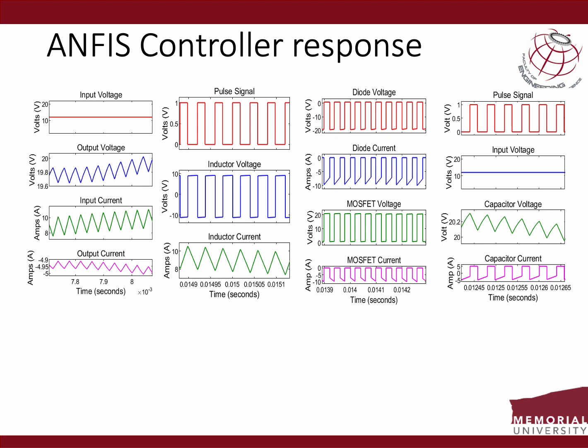During the simulation, we were also interested in the response for the voltage and the diode current. We were also interested in the voltages across the MOSFET and the capacitor. So all these were plotted, and we realized that the theoretical waveform and the waveform generated from our oscilloscope or our scopes were in sync, were correct, were in line. So it tells us that whatever we were doing, we were on the right path.